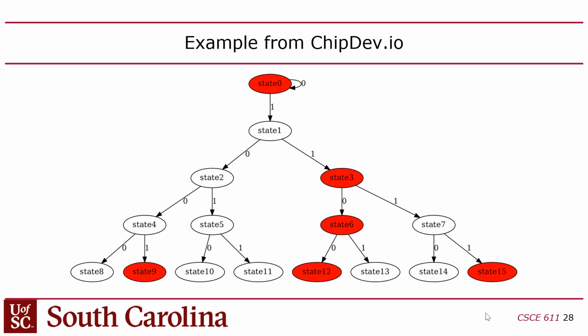So you look at this and you're like, okay, I've got 16 states. Obviously you could keep growing this tree out, but I've got 16 values, 0 to 15. How many of them are divisible by 3? 1, 2, 3, 4, 5, 6. So roughly a third. Now, how do I figure out how many states I need in my state machine, though?